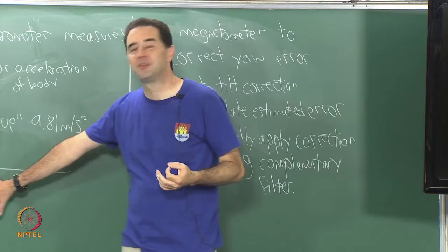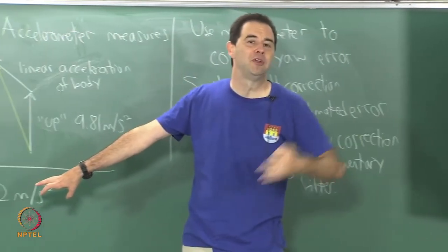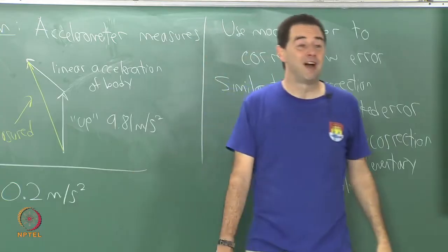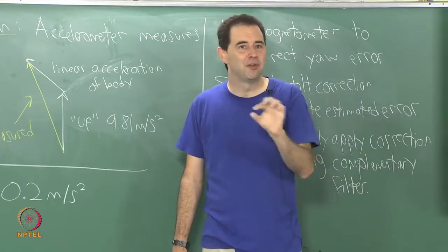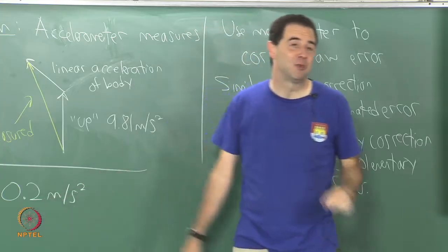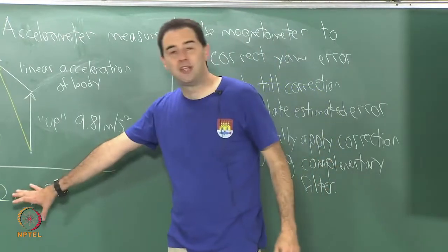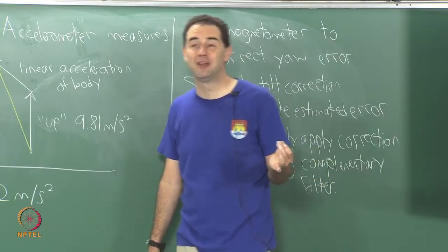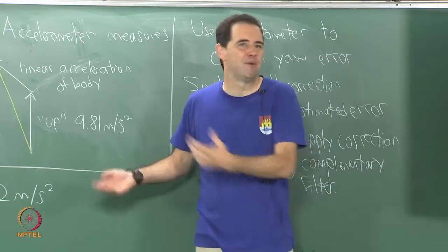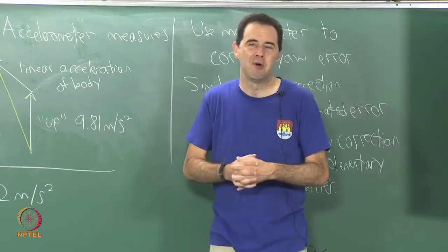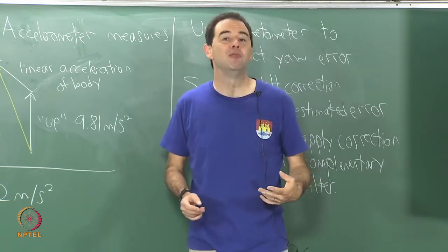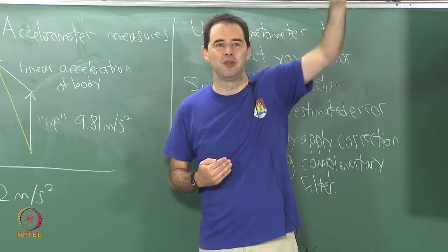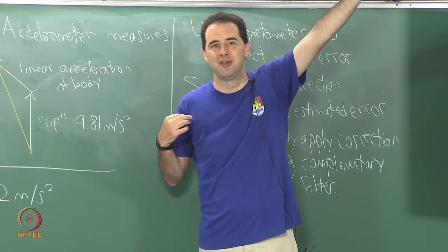And if you think you can compensate for this perfectly, then there's still the problem of double integrating noise, which will also be a very fast drift rate. But this quadratic term tends to dominate, because usually we have a very simple kind of bias or offset here, because we can't accurately estimate the orientation, and we cannot perfectly calibrate the accelerometer. So these are the difficulties we get into. And so we did a lot of experiments trying to do whatever we could, also adding kinematic constraints based on the human body, trying to rule out absurd possibilities that would cause a faraway drift, because we know that your head's not detaching and floating away into space.